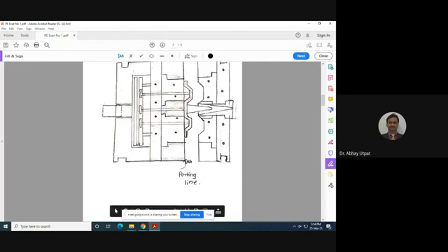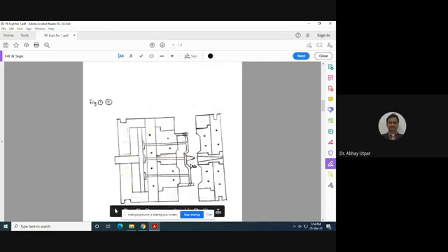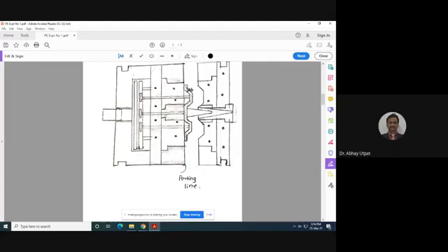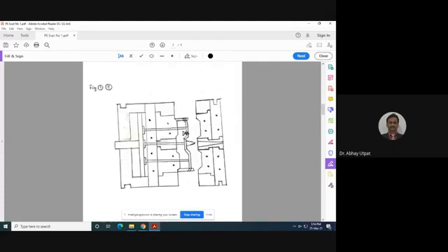One more thing, it is your parting line. And see, what you observe here, this product is in touch with the mold plate. And now these pins are forcing this product out of the mold. And now this product is out.